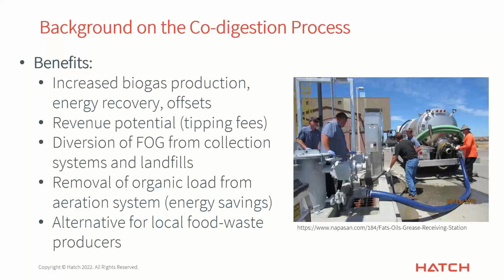And if you're looking at it from a very municipal wide point of view, it also is going to keep a lot of your organics out of your collection systems and out of your landfills. So if you are able to set up a FOG collection system for your restaurants and other food processing facilities, and they are having that kept on site and then trucked straight to your wastewater treatment plant, that's very useful. You don't end up with that problem where you have a lot of fat in your sewer system causing blockages and so on. And it keeps all that material out of your landfill and keeps a little bit more life to your landfill system.